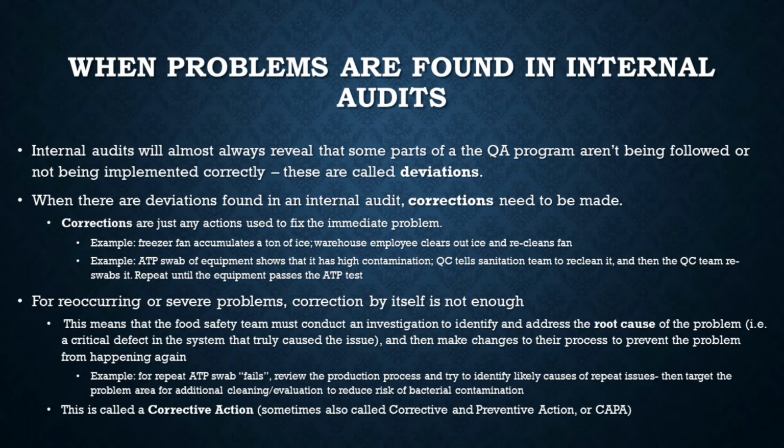Let's say you're cooking something for a safety reason, like a soup that needs to be cooked for 4 hours. I guess that'd be more like a stew, really. But anyway, moving on. So let's say you're cooking this stew and you need to cook it for 4 hours. Let's say you had to cook it at 250 degrees Fahrenheit for 2 of those hours. Well, let's say during that cooking period, a production operator notices that the temperature dropped for a few minutes, down to 245 F. They turn the knob up to keep the fire a little bit higher, and then the temperature goes back up, and that'll just be a correction, a simple fix.